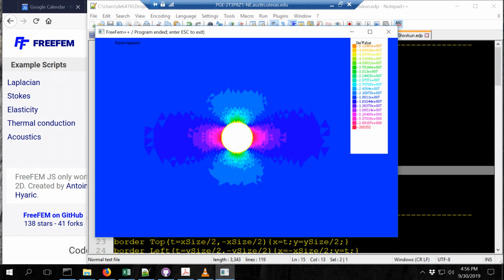If I have more stress in direction x, then I should have concentration of stress in here, in the top and bottom. If you see the values over there, they are all negative because in this convention and for this software, we're going to use compression as negative.